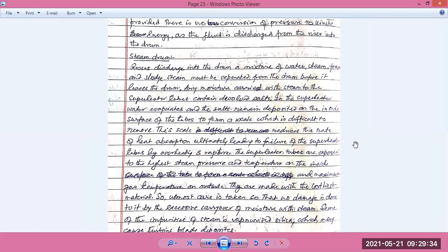If the density of water reduces, the amount of water moving per second also reduces, because we are supposed to have the natural circulation system between the drum, downcomer, riser, and the drum itself. So the heavier the liquid, the quicker and more reasonable the flow within this circuit itself.